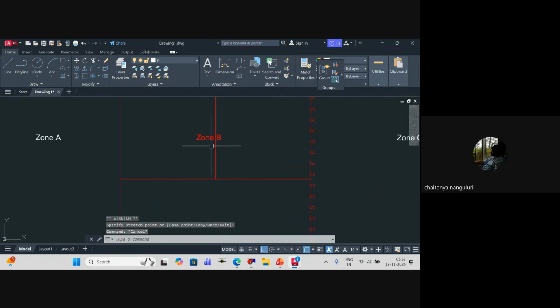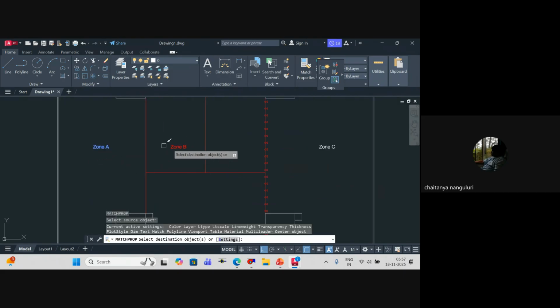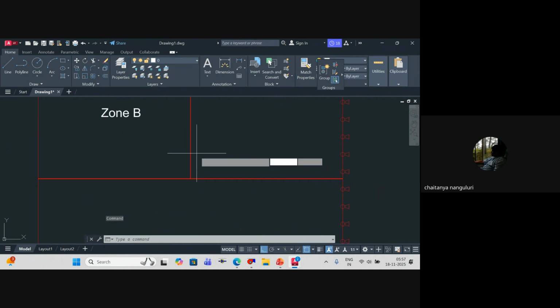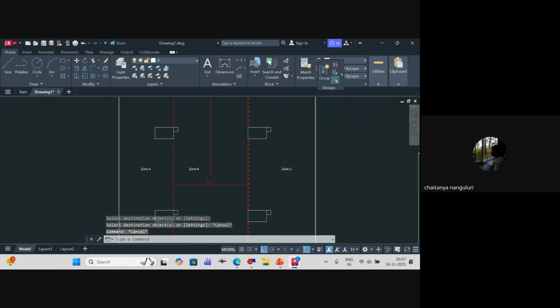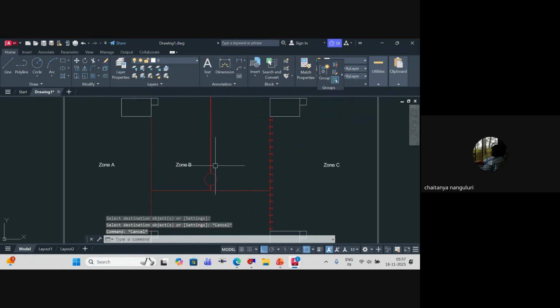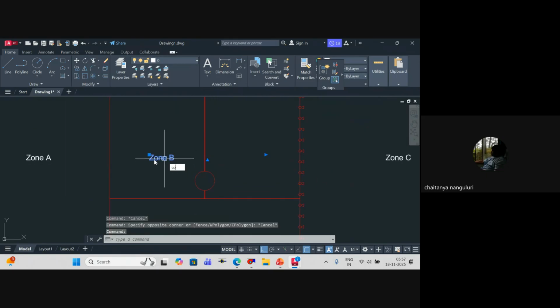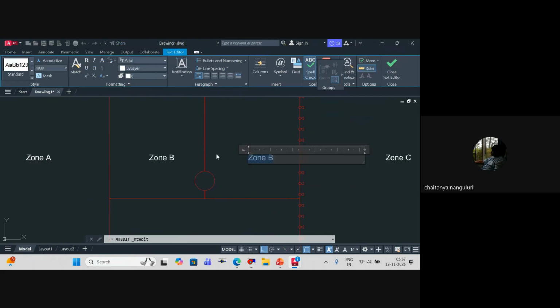So here, what we do is basically we will provide something called a deluge valve. That's basically a deluge valve with a simple electromechanical, kind of a solenoid valve. So whenever there is a signal from the fire alarm, the deluge valve will open. Understood? Okay. So this is nothing but your deluge valve.